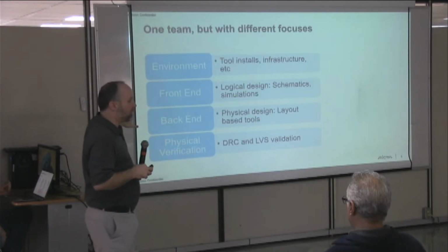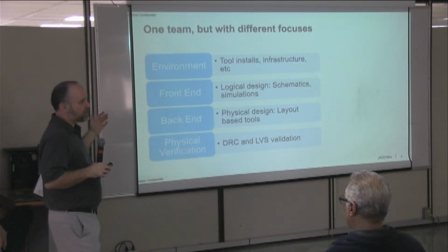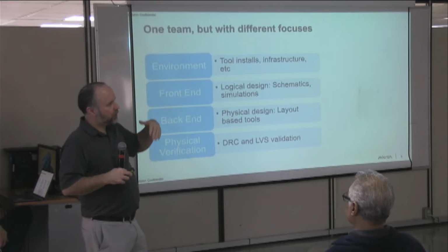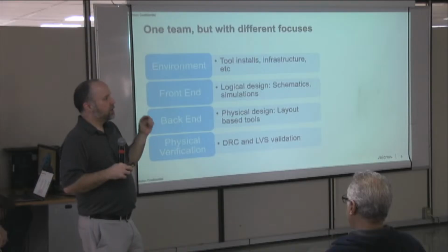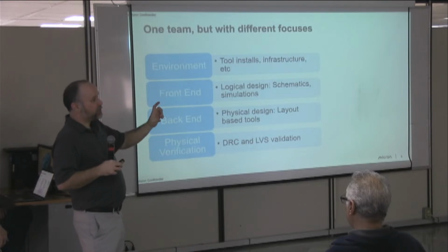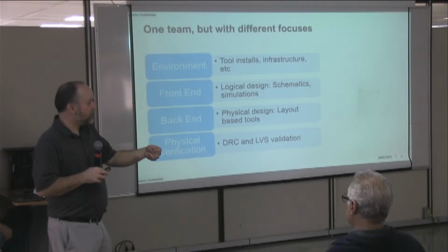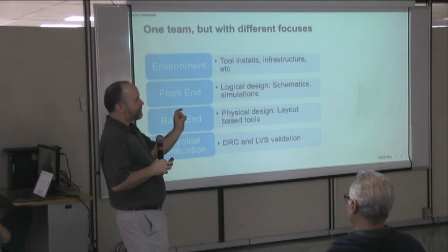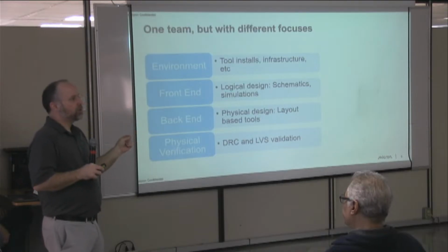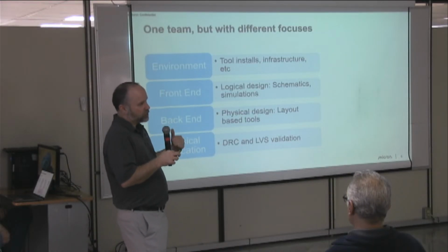And same for the stuff that we do. So my team, we have about 300 P-cells that we own. And P-cells, when you open the data, it runs the code and it evaluates and it builds the layout based on whatever parameters you've set. That execution time becomes very important because if your code is not so efficient, it takes a long time to open the data. And if people have to sit and wait, then they complain. Right? So we spend a lot of time trying to make sure that not only does the code meet all the rules, but that it's very efficient and that the time spent doing it is as short as possible.